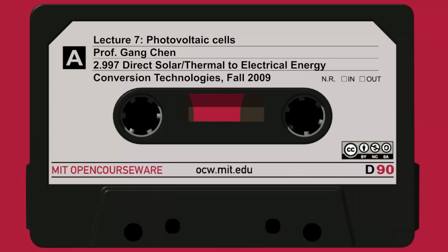What are the problems? Right? I mentioned for solar cells, the number one is a larger device. That's the key issue: a large device is very sensitive to recombination. So, what are the reasons for recombination? Those impurities, particularly impurities in the band gap, deep in the band gap, deep levels. Those are recombination centers.